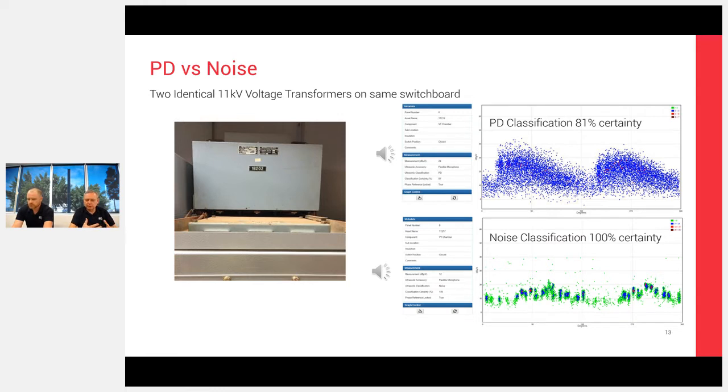Okay, so it's quite an aggressive crackling sort of sound. If it sounds aggressive, it sounds nasty, it usually is. That's a pretty basic rule that we go for ourselves there. So that one is classifying as PD. The clustering looks like PD and it sounds like PD to us.